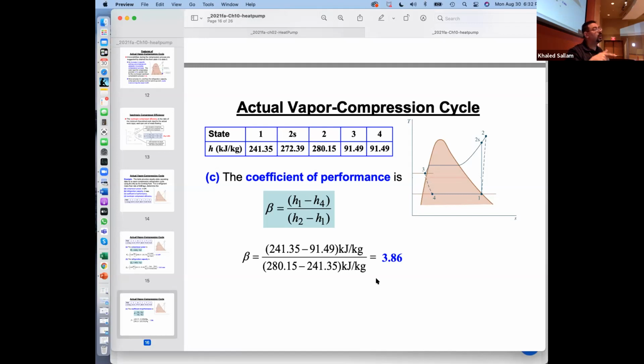So when I go to Lowe's and I'm looking at the heat pump they have for residential places, they will tell you it has a COP of 8. What is missing here? Should I just say, wow, pretty good, 8, I'm going to go and get it? Or should I ask about something else? Can someone just tell you your mile per gallon if your car is 40 without telling you is it highway or downtown? You need to know how this is measured. Yes, you cannot just say COP without telling me when it was doing what.